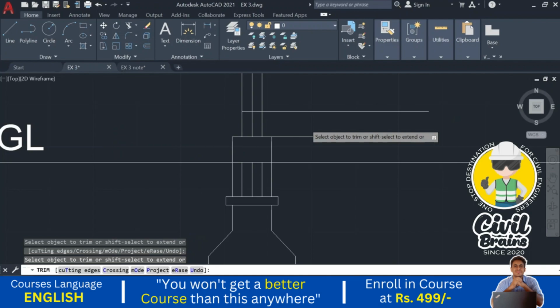We have discussed in the previous examples how to do the section, the procedure of the section, and here also we do the same. The first step is to take the center line of the walls where the section line is passing. We need to draw first the center lines of all the walls where the section line passes: 1, 2, 3 and 4. I draw all four walls' center lines using the construction line.